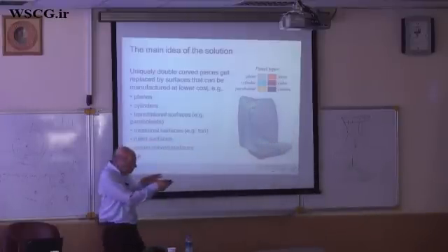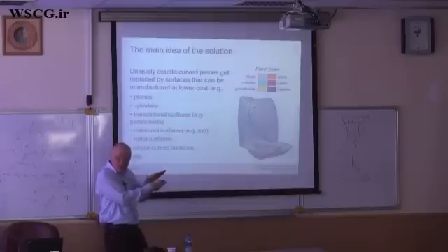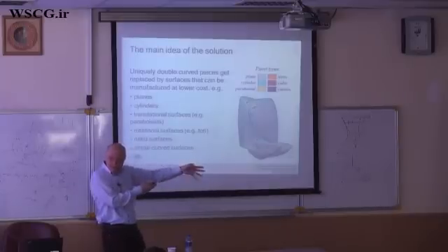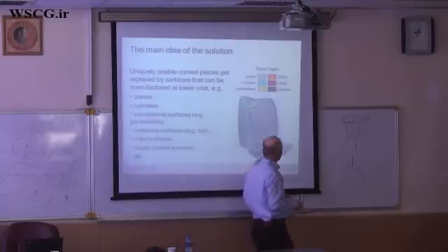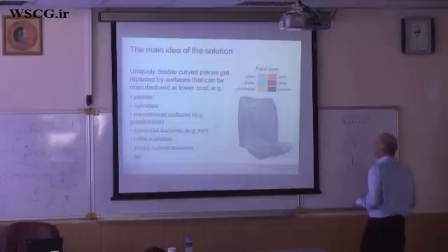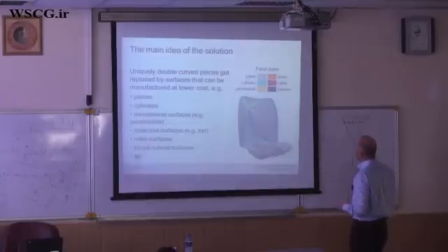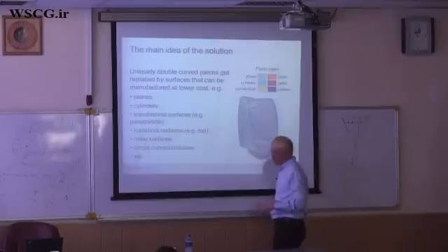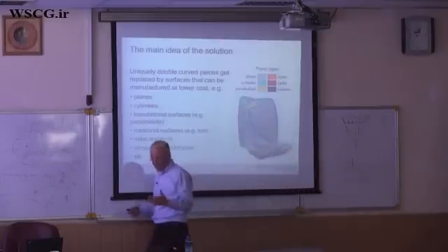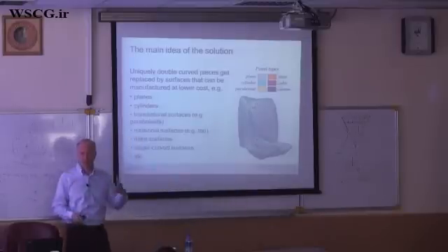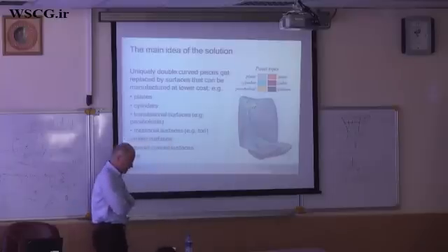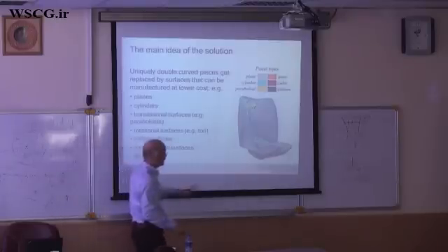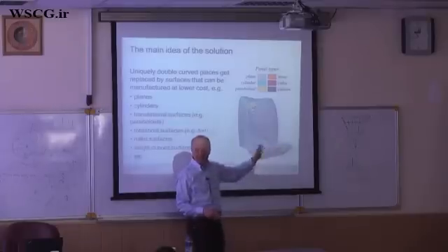Feature, I mean areas where you have in one direction close to zero principal curvature, in the other direction higher principal curvature, and this is natural to use here cylinders. And then you have some nasty cases, and the most nasty case is actually here the cubic. The cubic just means you have like a cubic Bezier patch or so. So a more complicated patch, which definitely would require the making of a mold. But if they are rare, these cubic patches, say it is still feasible.